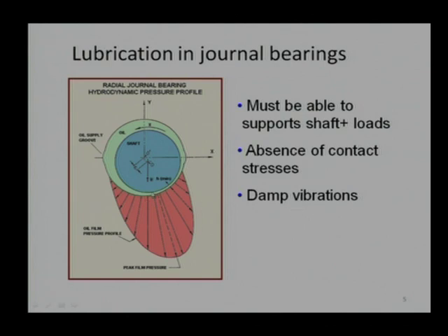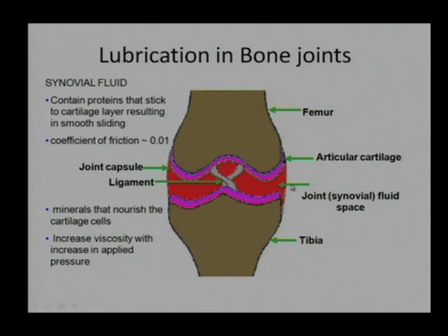We are not counting the temperature aspect here, because that will depend on the application. If it is used in a compressor, the temperature will be different than in an IC engine. Those temperature requirements will come along with applications, but purely from the bearing point of view, these requirements are sufficient. So, if your lubricant is able to satisfy these requirements, we will be happy.